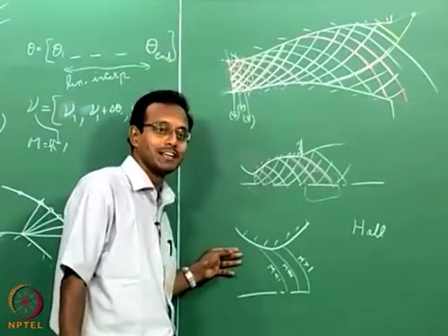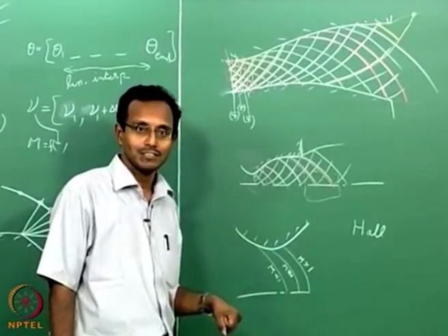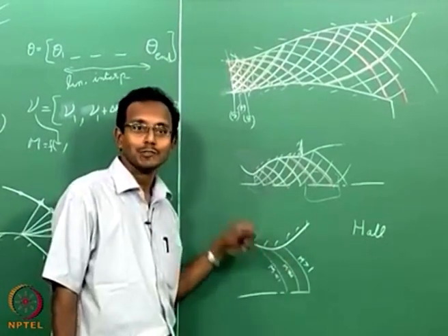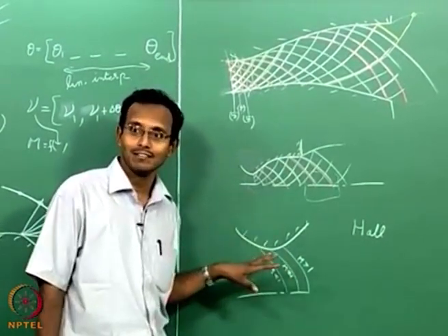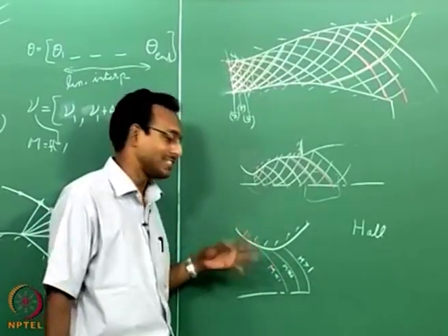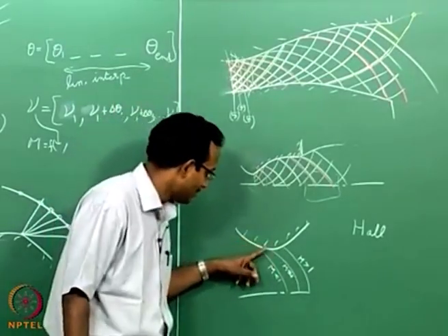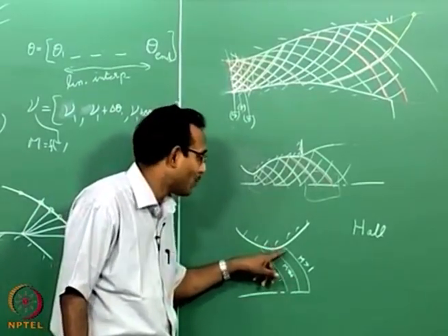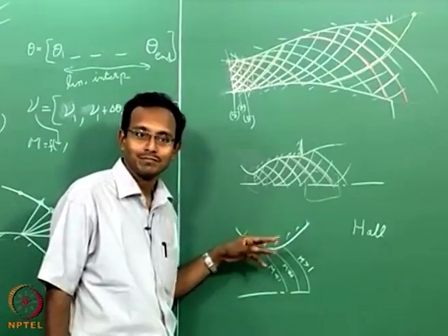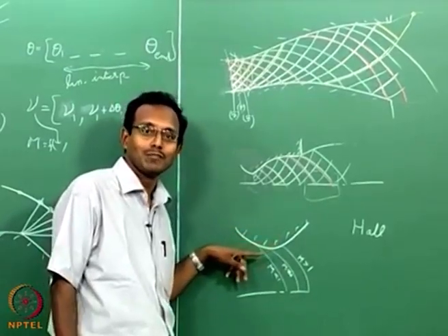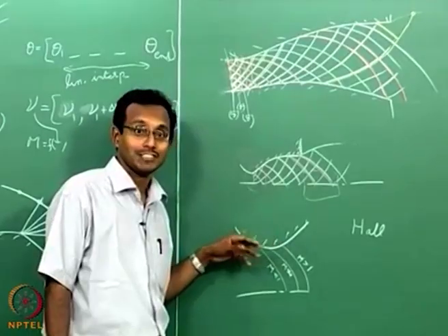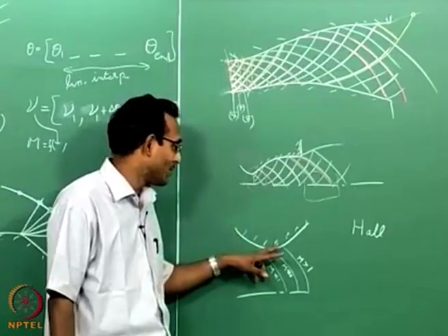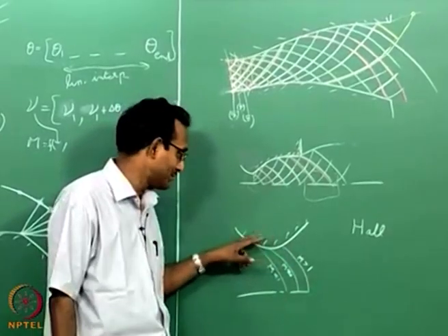We have used this data and created nozzles, and they work well. We used that kind of starting line and then used MOC to create nozzles, and that nozzle works well. So I will say that data is reasonably close. We typically do not use the M equal to 1 line. We will typically pick 1.1 or 1.05, and the solution is not very valid for more than M equal to 1.2. It is transonic, the errors will become higher for M more than 1.1. So, I typically use 1.05, 1.1 kind of numbers.